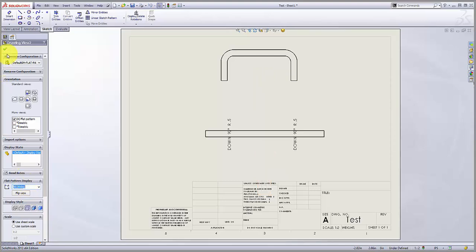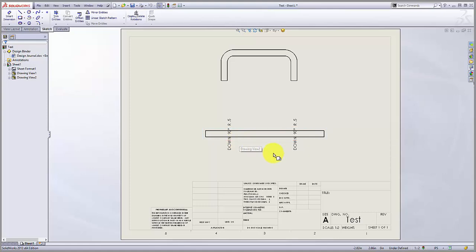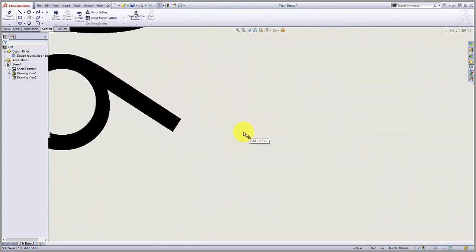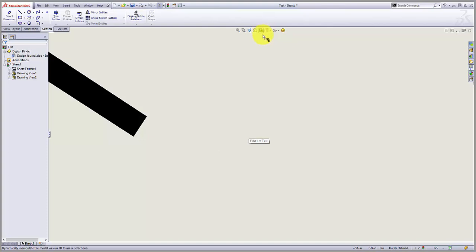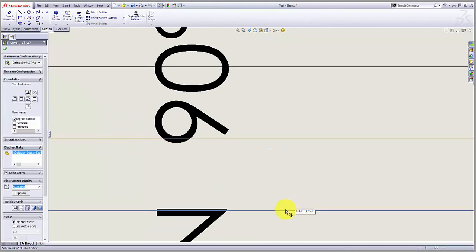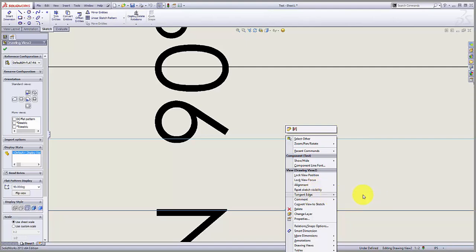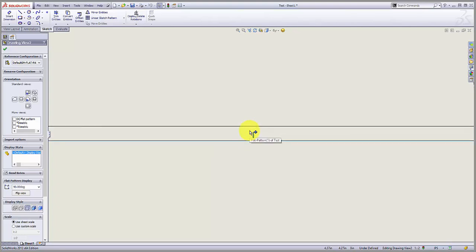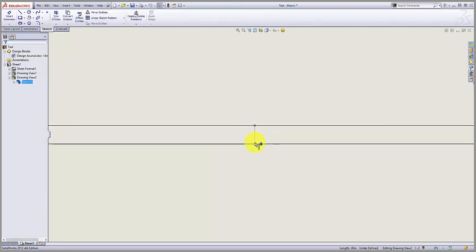We flip it, great. You say, wait, where are the bend lines? Well, if you remember, that surface is only 0.0002 wide, so our bend line is only 0.0002 wide. And if we make those tangent edges visible, and we zoom in, you will see that there is a bend line.